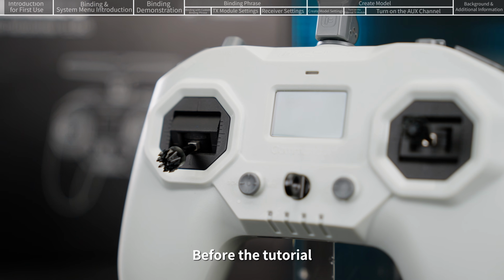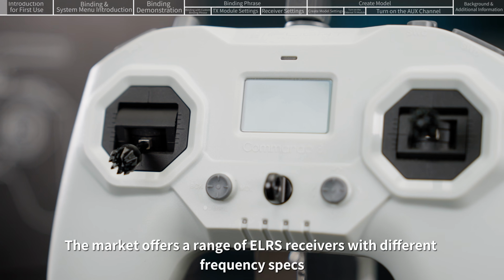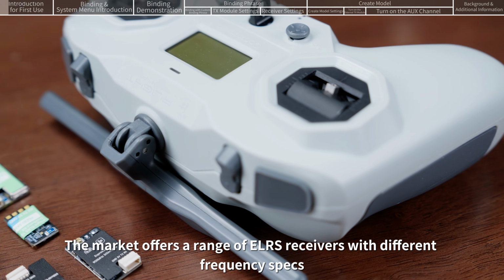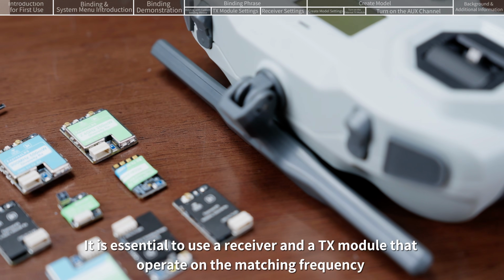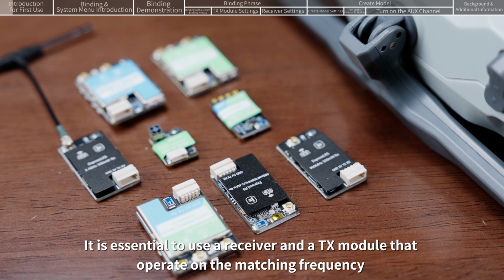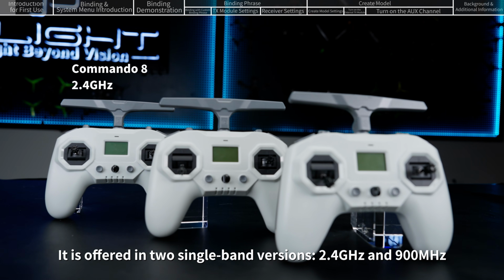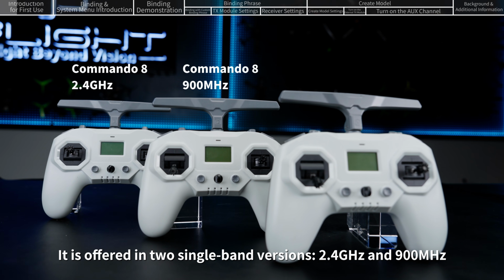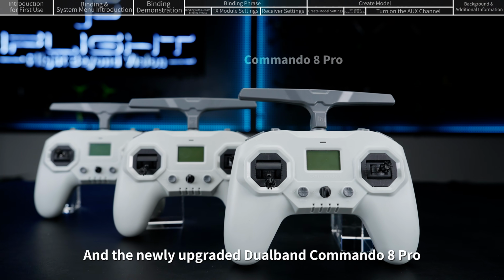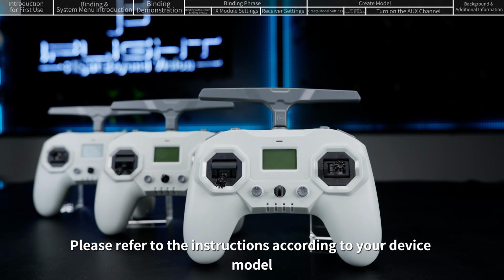Before the tutorial, let's start with an introduction to the frequency compatibility of ELRS. The market offers a range of ELRS receivers with different frequency specs. It is essential to use a receiver and a TX module that operate on the matching frequency for successful binding. Using the Commando 8 as an example, it is offered in two single-band versions, 2.4 GHz and 900 MHz, and the newly upgraded dual-band Commando 8 Pro. Please refer to the instructions according to your device model.